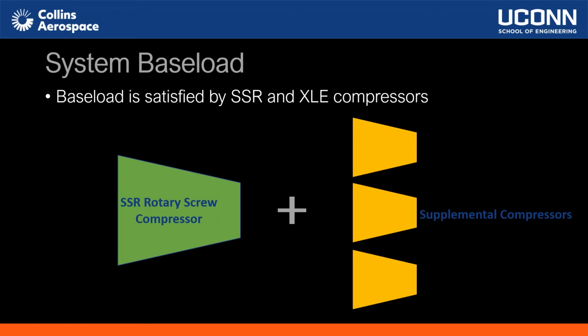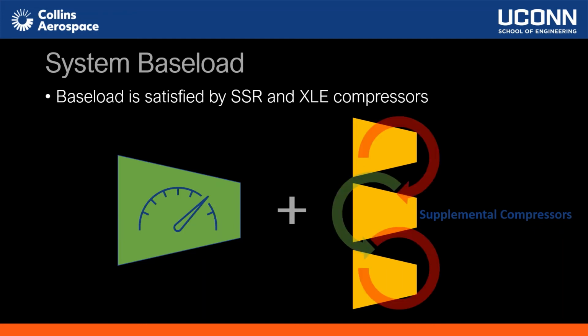To satisfy the baseload condition and plant demand, one of the SSR compressors runs at full speed, while the other compressors cycle on and off to satisfy the remaining pressure requirement. To more efficiently cover the baseload at Collins Aerospace, we will use our developed model to recommend the best compressor combinations and offer advice regarding which compressors that are at the end of their operating life should be repaired versus which ones should be replaced.